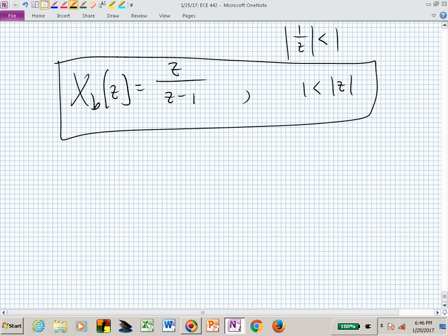And in the z-plane, this is now the z transform. Does that look sort of like what we had for S? I'm sorry, in the S domain, it was 1 over S. We're going to find that S equal to 0 is similar to Z equal 1. So now, where is our pole at Z equal 1? We actually have a 0, a finite 0 here.